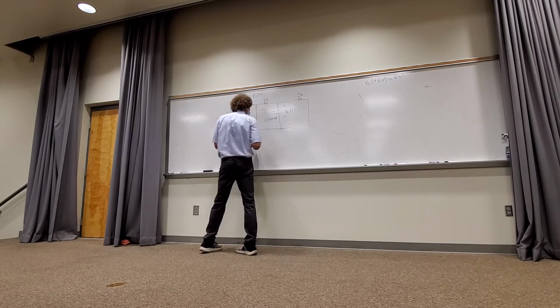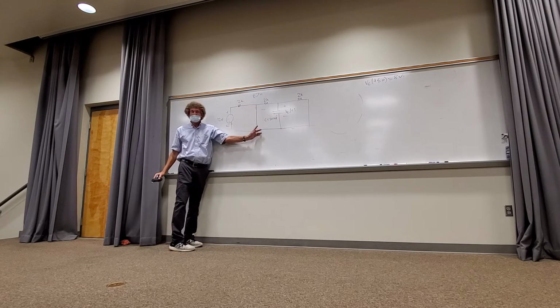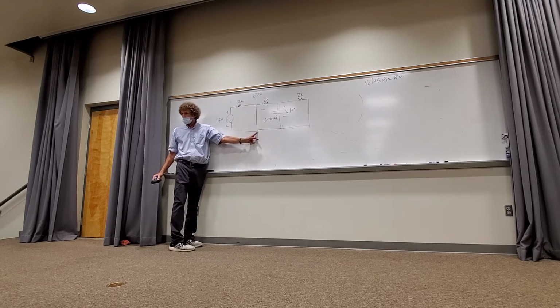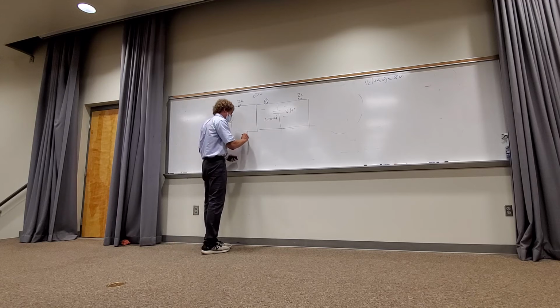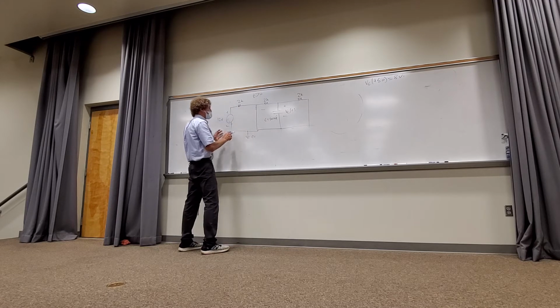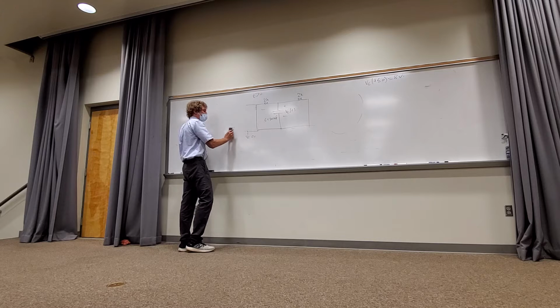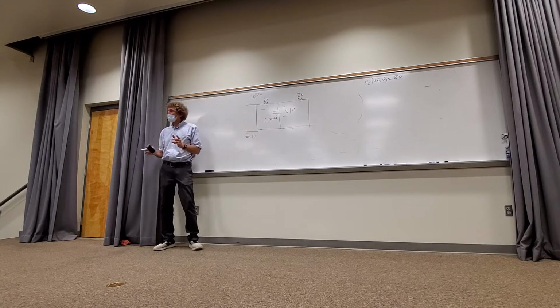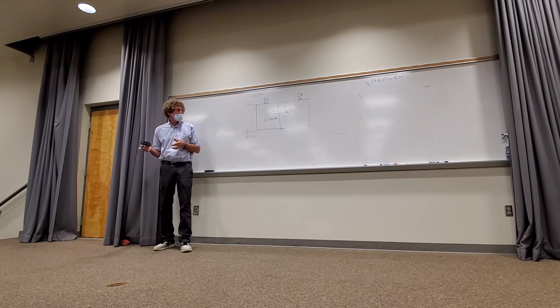Now, this point goes to ground, doesn't it, class? Do you all see that? Because the switch closes, these two have the same potential. If you want to put a ground there, you can. Which means this part of the circuit is gone as well. Anytime you take something shorted to ground, whatever's on the other side makes no difference. Y'all follow me? It literally isolates that portion of the circuit.